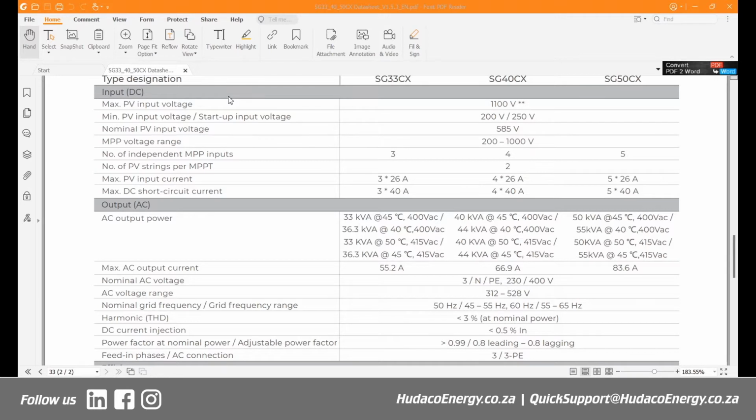Most people would say there's no problem as long as I'm within the range. The range, of course, is a determining factor, but be careful about the efficiency of your inverter. When you find your inverter below a certain value, the efficiency also goes down with that, or above a certain value, it goes lower. Okay, so normally if you can start around 585, 600 volts, somewhere there, it has got the highest efficiency. All right, so let's go ahead and see.